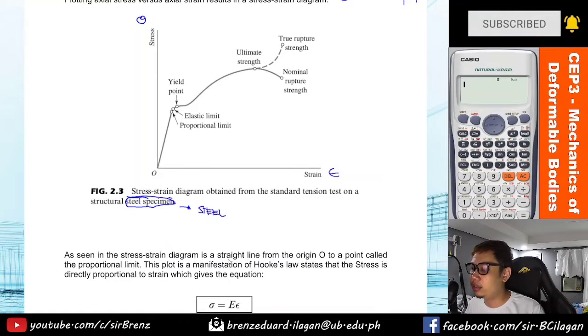So, as seen in the stress-strain diagram, is a straight line from the origin to a point called the proportional limit. So, dito, proportional pa yung value. As you can see, when you increase the stress, the strain is also increasing. And at this point of the proportional limit, kapag binitawan mo daw or nirelease mo yung force na naka-exert sa kanya, babalik ulit siya sa original shape. Okay, so yan yung proportional limit.